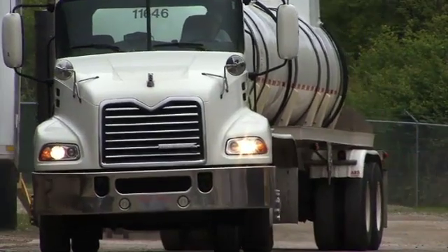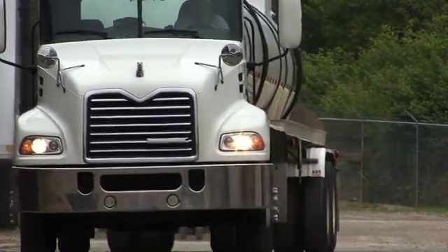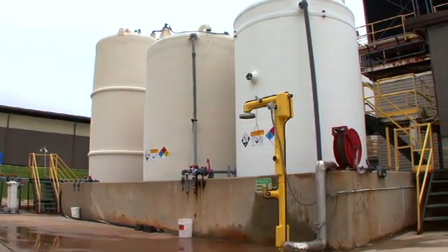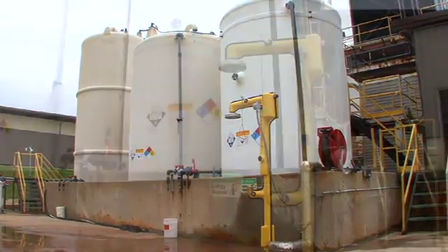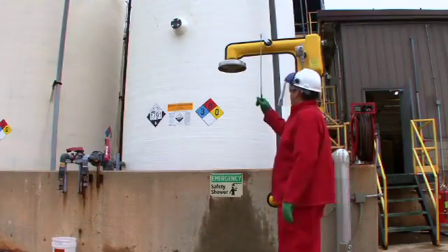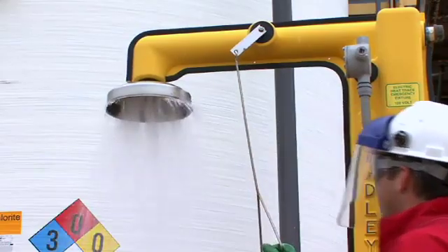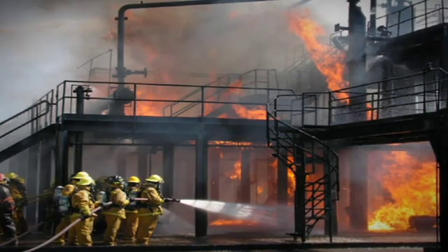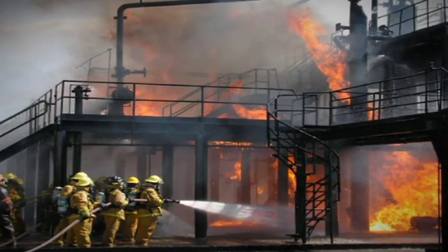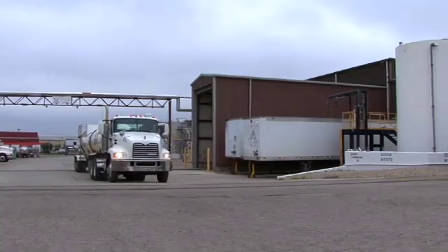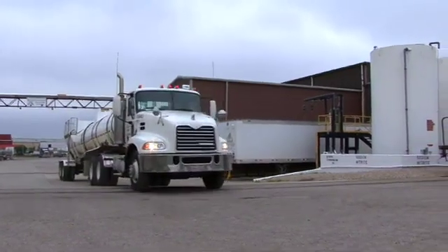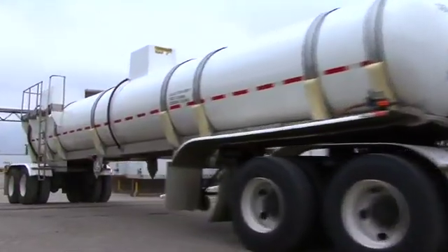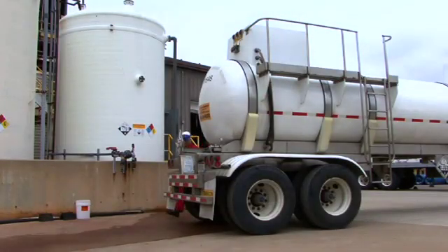It's important to ensure the truck driver complies with the facility procedures as well. A safety shower and eye wash fountain should be located close to the unloading operation. They should be checked to make sure both are working properly prior to unloading. Accidental mixing of incompatible chemicals can result in severe consequences. Clear communications and coordination between the truck driver and operations personnel is important for a safe unload process.